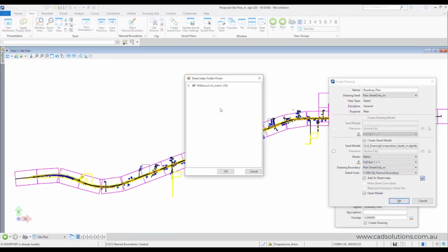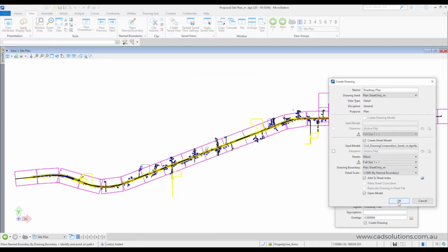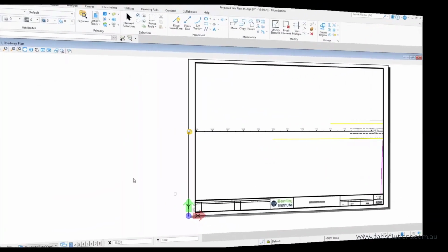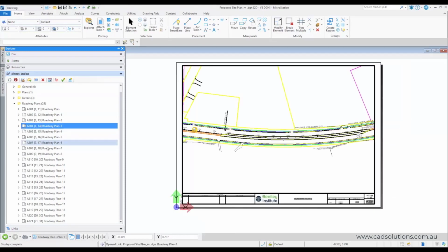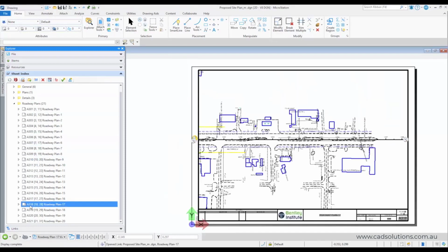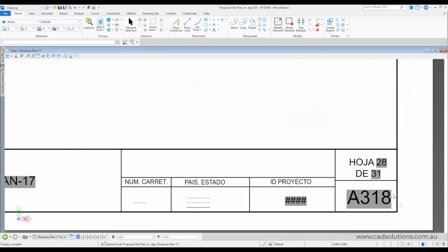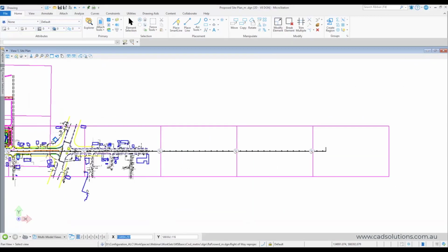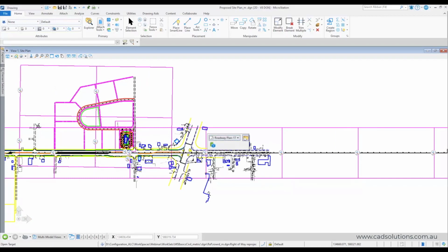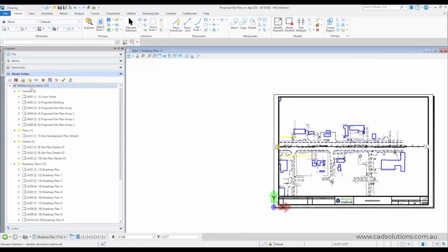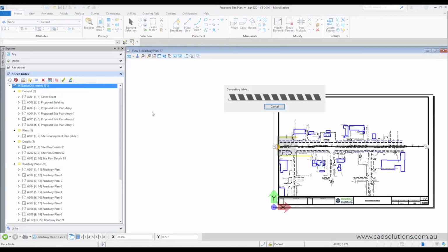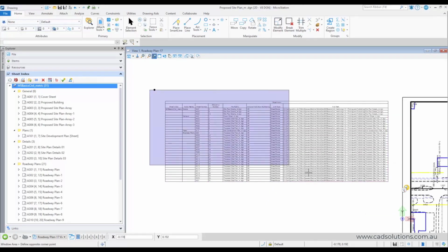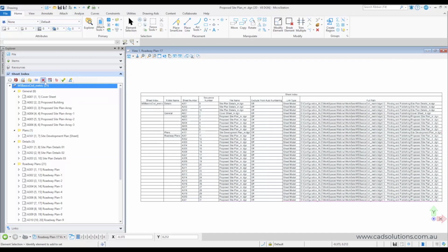MicroStation offers the Drawing Boundary and Named Boundary features to simplify the cumbersome process of sheet creation and further enhance the dynamic views workflow. Using a drawing boundary, you can quickly and easily define the location of a drawing. You can place multiple drawing boundaries on a sheet model. These drawing boundaries can then be populated with content. You can organize the sheets in a sheet index by different categories. Each category is a different folder in the sheet index.